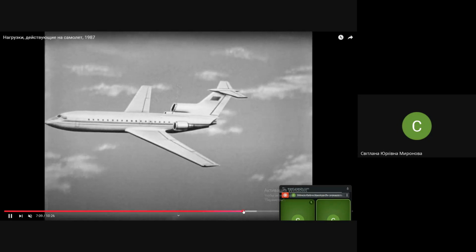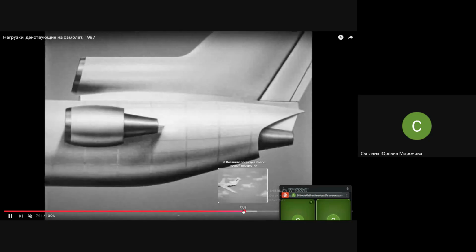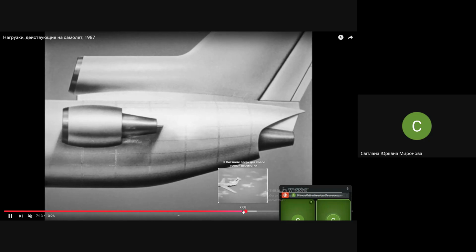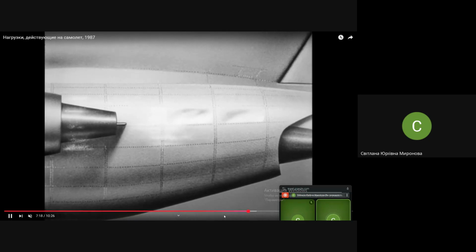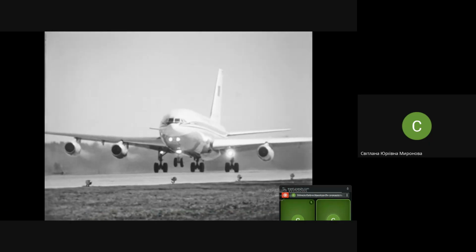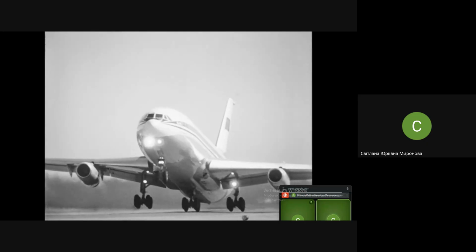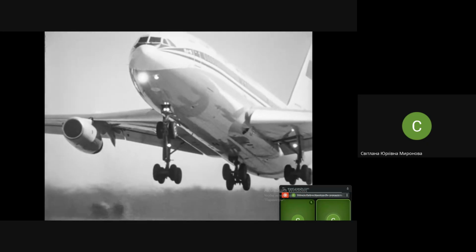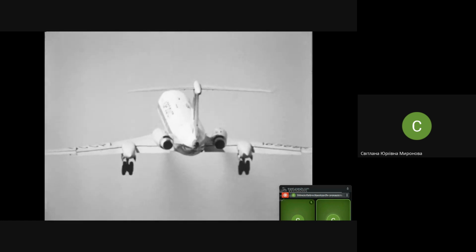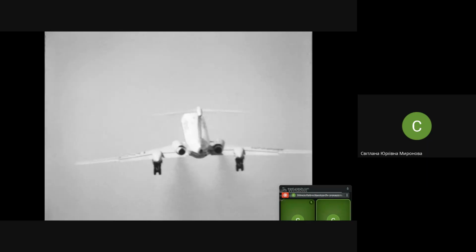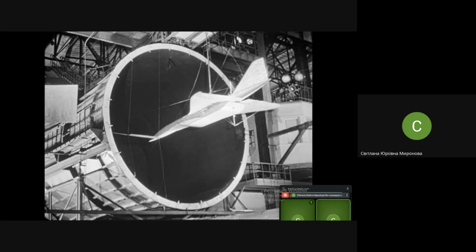That extra loading may result in a fatigue problem. Fatigue means that after cyclic loading, the structure may crack immediately, even at low stresses, at low loads. Or the cracks may grow, increase in size, grow dramatically, and the result is the whole breaking of the structure.